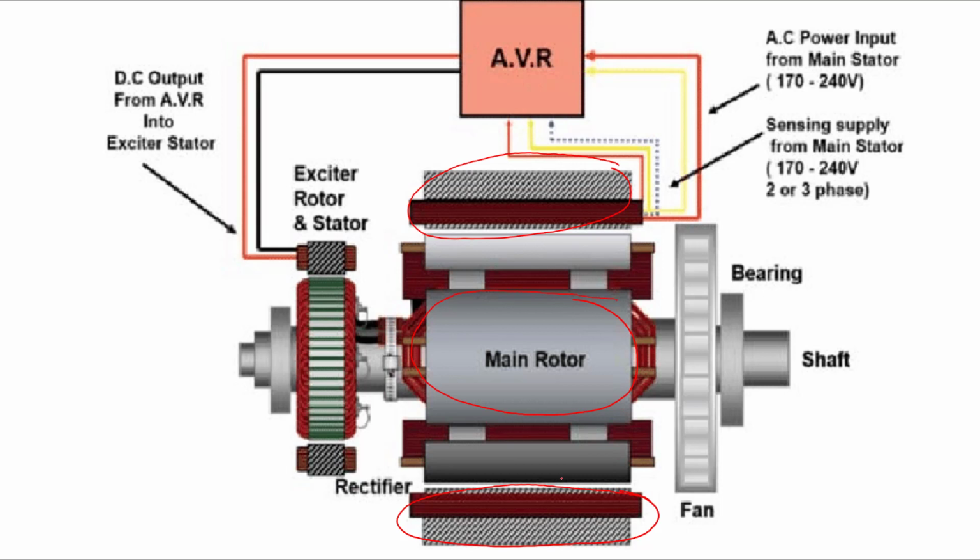And that is why it is essential to put the armature winding on the rotor in case of a DC generator. But now the question is, why do we need to put the armature winding on the stator in case of an alternator or a synchronous generator? It would have been operated best if it is put on the rotor, right?